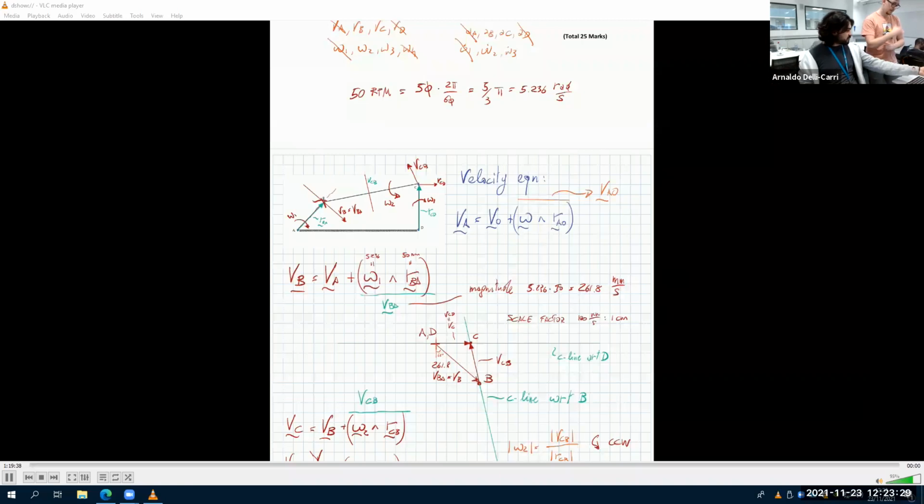In fact, if omega 1 is clockwise, you get this. If omega 1 is counterclockwise, you go the opposite one. So we're constrained to saying that it's clockwise. Would that other one be right as well? No, because in this particular case you're doing omega 1 clockwise, and at this instant of time, this is the acceleration value. At a different instant of time, it is a different one. So this is for this instant of time, when this is going clockwise.